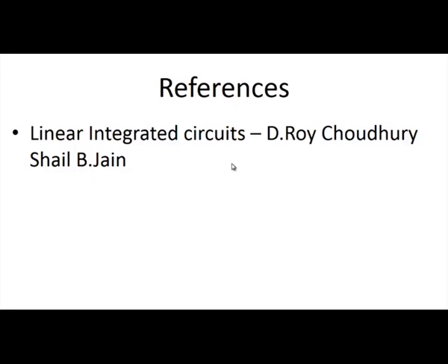One more important point is that in the RC phase shift oscillator, the input resistance given to the inverting terminal of the amplifier must be 10 times the resistor present in the feedback network. So, these are the points you have to remember for designing the oscillator, either an RC phase shift oscillator or a Wien-Bridge oscillator. We have designed an oscillator for a frequency of oscillation of 100 Hertz for both the oscillators. These are the reference.